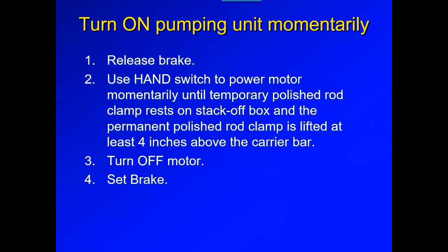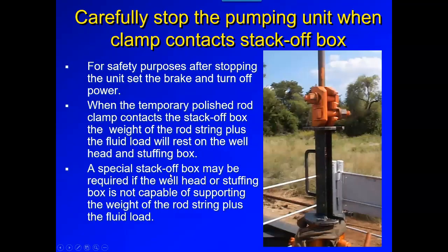With the stack off tool installed, we're going to release the brake, momentarily turn on the pumping unit, stacking off the well, creating separation between the polish rod clamp and the carrier bar. We're going to turn off the pumping unit and then set the brake. Now, this is a well in which you can see that the polish rod clamp is resting on top of the suitcase. Okay.